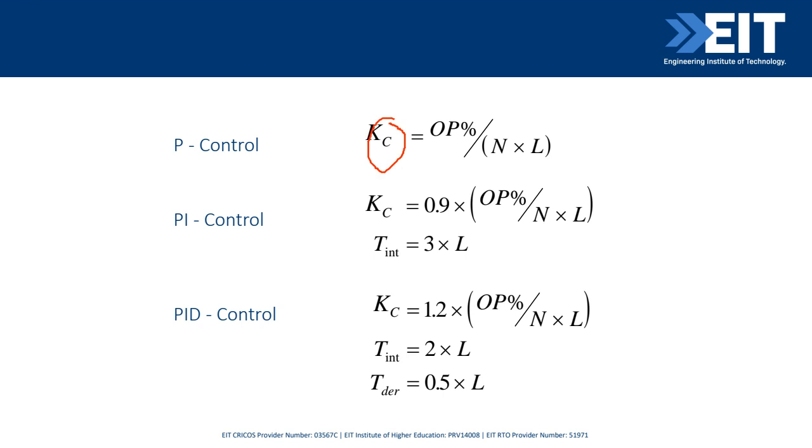That, unfortunately, on its own, when you set the tank level target set point to 82%, you'll always get your process variable to go to 83 or 84 or 80%. It'll never get to the target. And as Lance says, it's because of the offset error. There's always a bit of offset. And how do we get rid of the offset? What do we add to the mix?